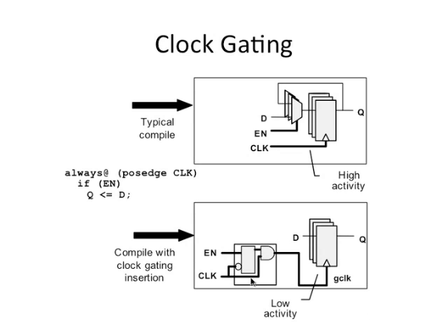Of course, what you have to keep in mind is that when you introduce this kind of circuitry in the clock path, the clock signal has to travel through an extra AND gate out here, right? Now imagine there is another flop somewhere which is creating the data which eventually comes to this, the previous flop in that pipe stage. So now you have to worry about timing closure, because you have introduced skew in the gated clock.